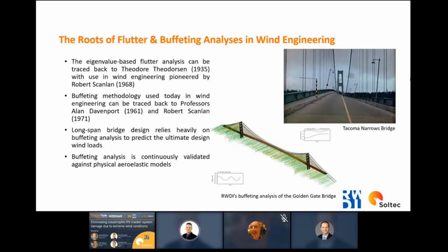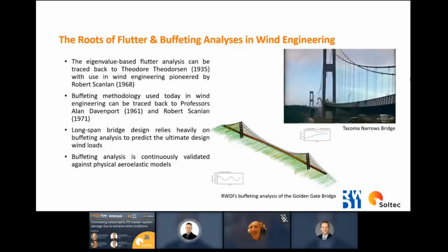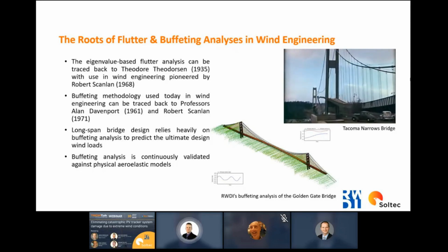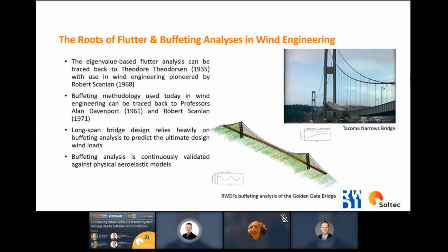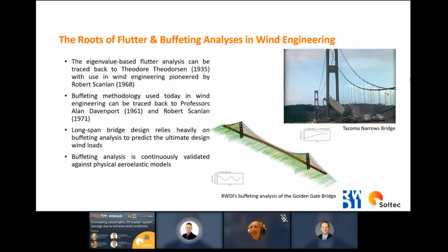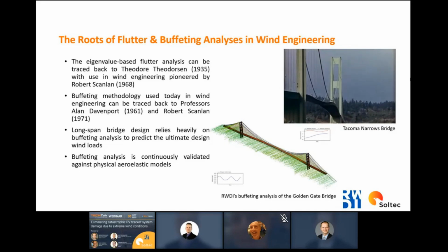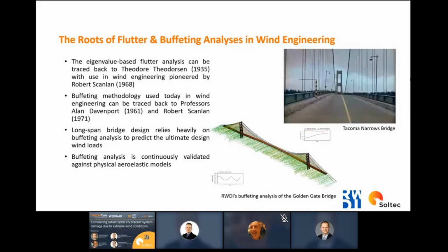And then the buffeting methodology that we use today was started in its infancy in the 1960s and continued into the 1970s. And long span bridges rely heavily on the buffeting technique to produce design wind loads. But one thing that is important is this buffeting technique has been validated against physical aeroelastic model testing over and over again.